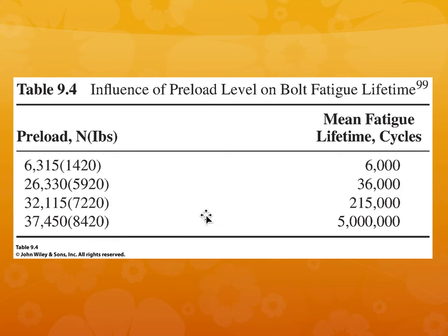For example, if you apply a very large preload of 8,420 pounds, the mean fatigue lifetime goes up from 6,000 to 5 million cycles.